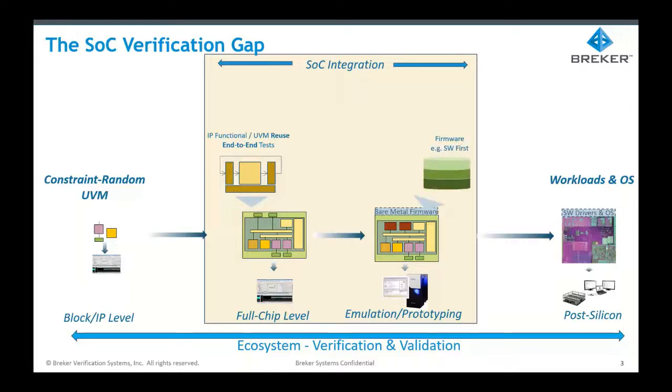At the other end, when you're doing prototyping, you want to have firmware development starting early before you get silicon. However, there is also a number of tests and verification tasks that you need to complete during this phase. For example, your coherency, power management, connectivity, can you boot from all the devices? And one of the issues that we have today in the industry is that there are no best practices of what's the better platform to run some of those integrity tests.